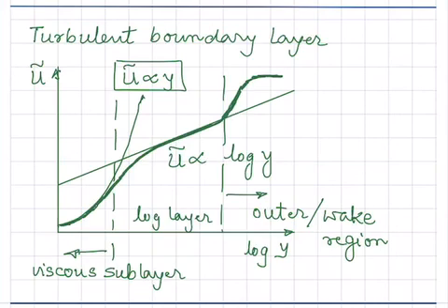This is true for all boundary layers. You would always have a region which is very close to the wall, where turbulent fluctuations are very small, trying to meet the no slip condition at the wall. That happens to be the viscous sublayer, and viscous effects are large. They damp out the velocity fluctuations. Then is the log layer, which is where turbulence picks up and has a dominant effect, and the outer layer is actually large turbulent fluctuations towards the edge of the boundary layer.